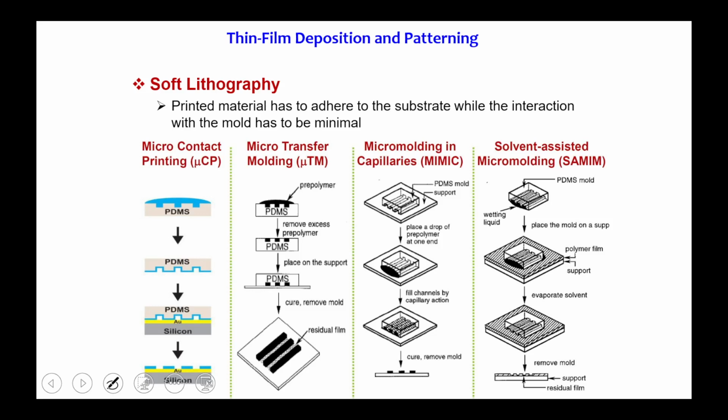So micro contact printing, where you can design in the micrometer range, uses PDMS layers here. This is the silicon, and above that you use the PDMS layers. So these are the types of structure you have to obtain in that case. This is the fabrication method, with the steps you have to take during soft lithography.